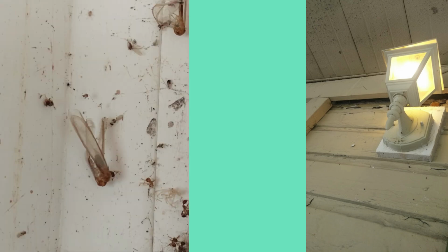In the current image, you can see we're inspecting a home with old wood siding. You can also see that the paint was flaking away, and it probably wouldn't surprise you that we found drywood termites on this home. One thing we found in a spider web really close to the spot you're seeing by the light was a drywood termite swarmer. So you need to look for things like swarming termites that may get caught in spider webs. Now, it wasn't even the time of the year that these types of termites would be swarming. It was actually in the winter.